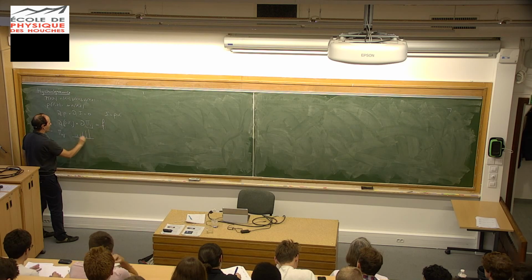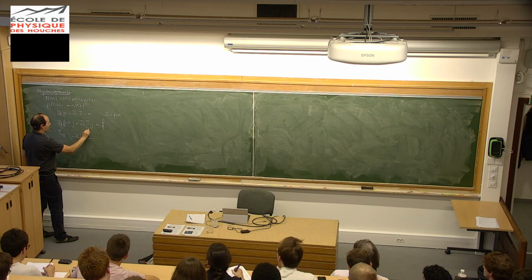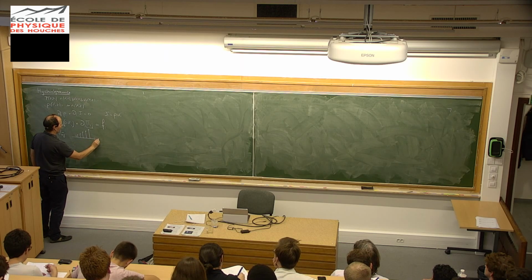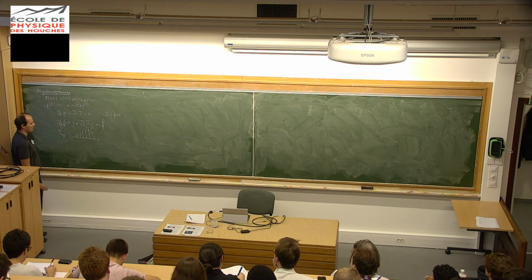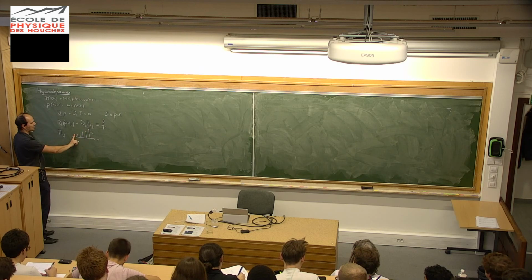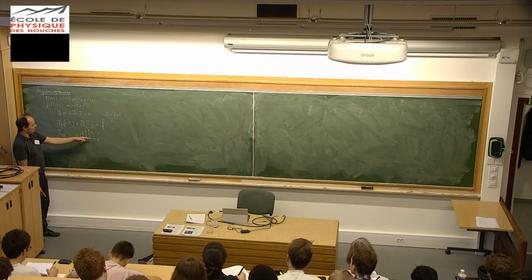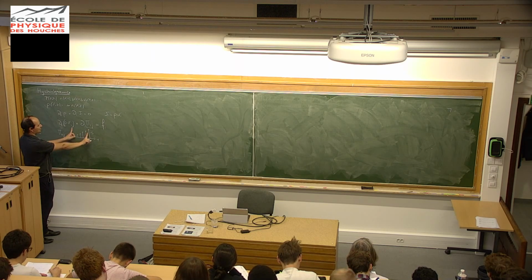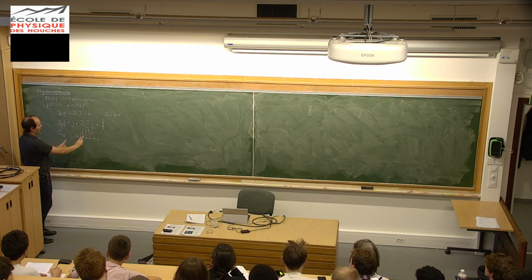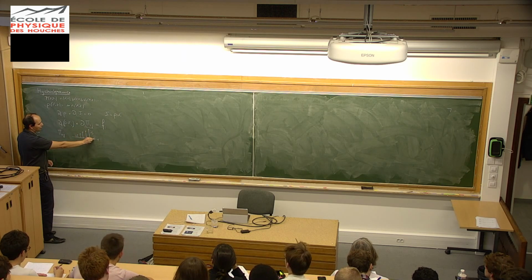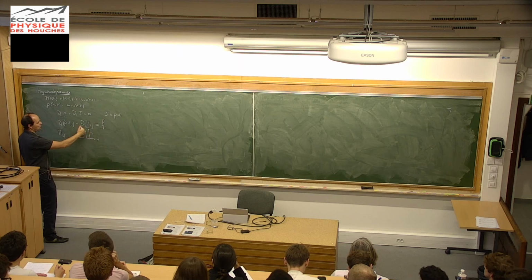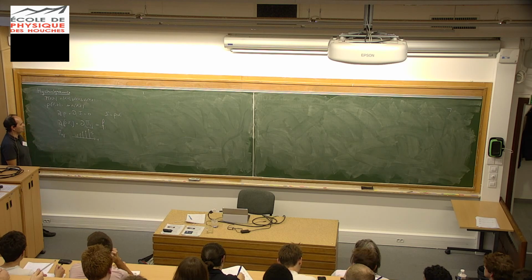So if you have, for instance, a gradient of velocity, so I plot here the velocity along y, and so this is a coordinate x of the velocity. So I have a shear velocity along x in this direction. So the velocity along x varies along y, and so I will have a transfer of momentum along x because this velocity will tend to equilibrate. So you see, I can create a flux of momentum in the direction y because the particles which are here will transfer momentum to there to equilibrate the momenta along x. So this is the meaning of these components here, of this flux of momentum.